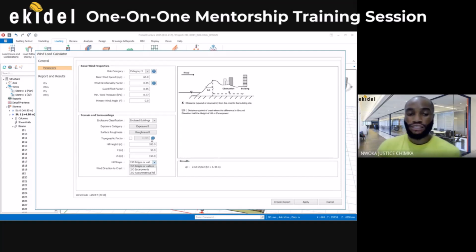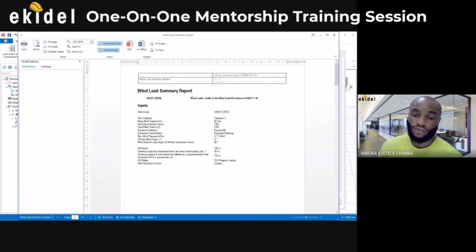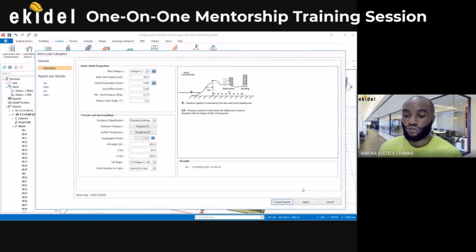Once you have done this, you can choose to come here and create a report for it. Just click on report and hold on for it to generate the wind report. Wait for that, then you can see the wind reports here. You can choose to save it as PDF or Word. Once you've done that, you can close it, then click on apply.